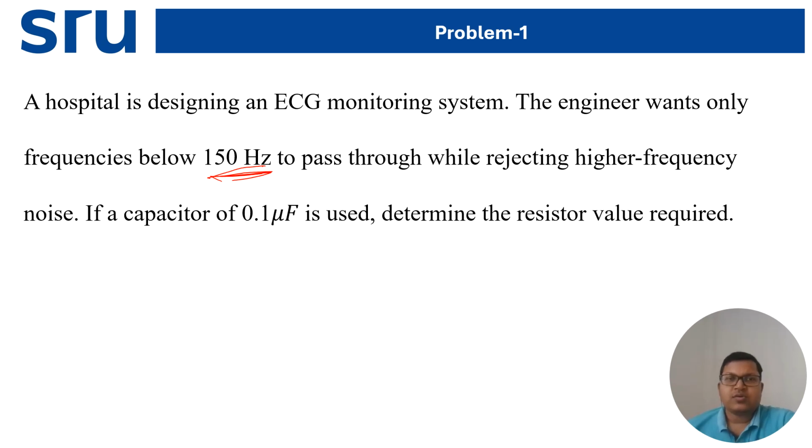So that means this is a high pass filter, right? Sorry, it's my mistake. It will be a low pass filter, because it is asking to pass only the frequencies up to 150 Hz and reject all the other frequencies higher than that.